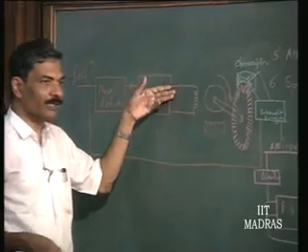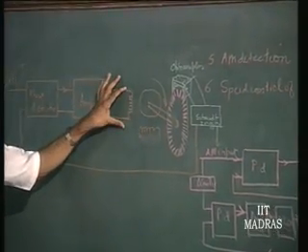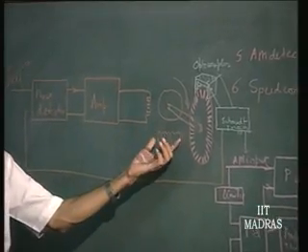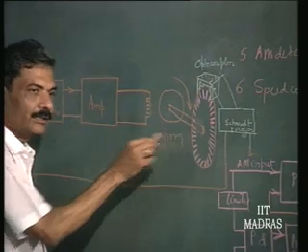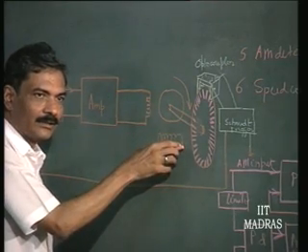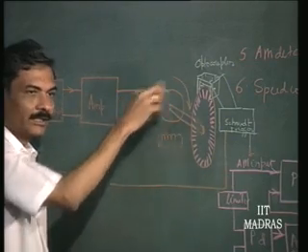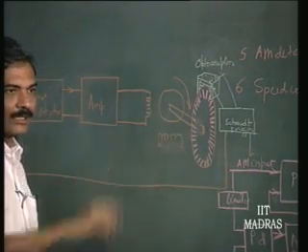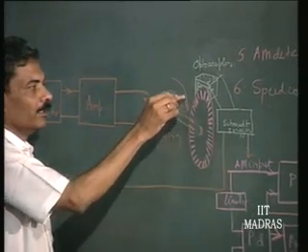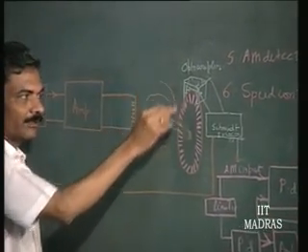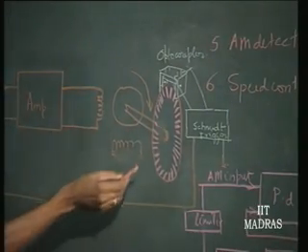So, this is applied through a power stage if necessary to drive the field winding of a motor. This is the other winding. These are the two control windings of a motor here. So, if it is given constant voltage here, this is going to be given the control voltage here, so that the speed is controlled, speed and the direction can be controlled using this. Now, the speed of this motor is converted to frequency using what is called an optical tacho.